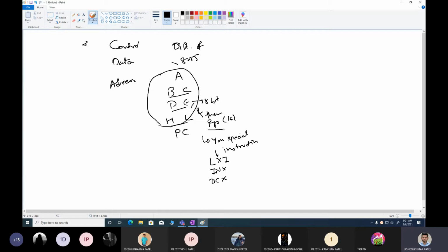Other than that, we also know there are some control signals. Let us describe which signals we know. The first signal we know is the read signal, the other one is the write signal. We also know what ALE is. ALE is the address latch enable signal. We learned this signal during the timing diagram.